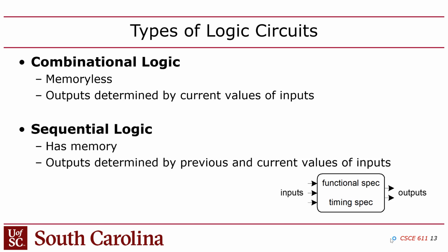But in order for that to work, you need a 7-segment decoder, and you might have designed something like that in 211. A 7-segment decoder is a circuit where you give it 4 input values, basically a value between 0 and 15, or 0 and F in hex. And then it converts that to 7 output pins that each go to the 7 segments of one of those numeric LED displays. And so that's combinational, because if you update any of the input pins, it's going to immediately update the output, right? And so the output will only be a reflection of the current input.